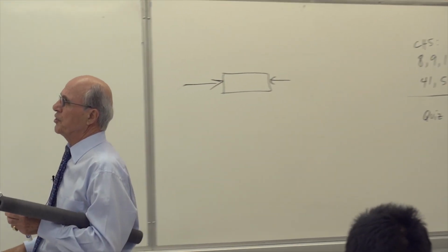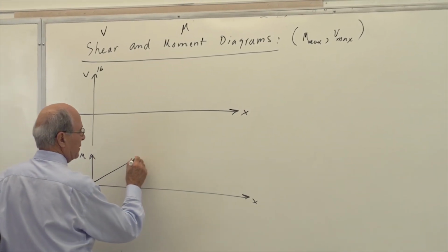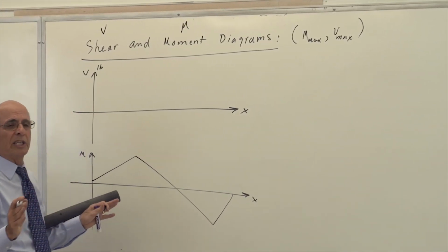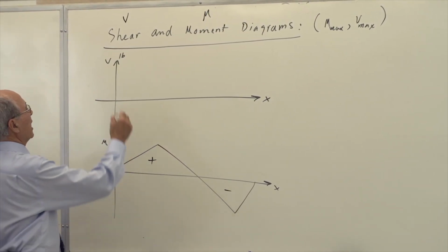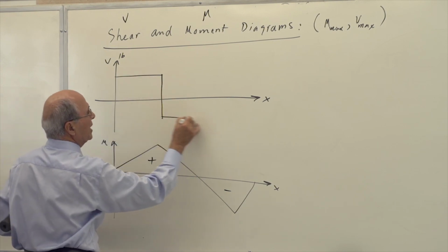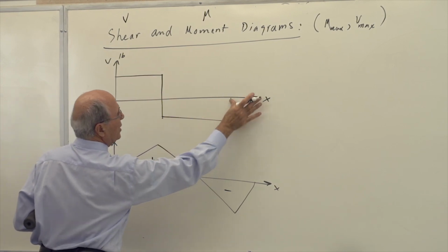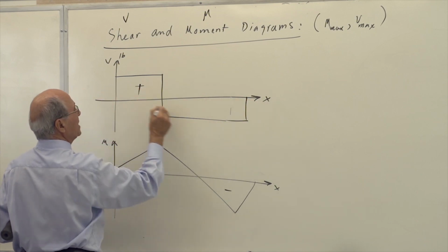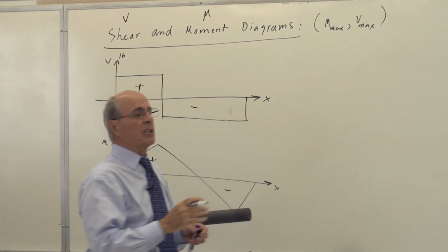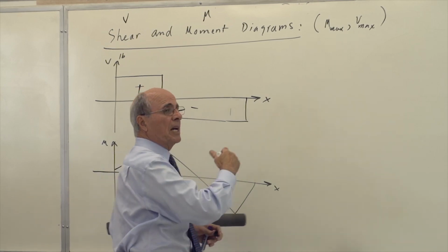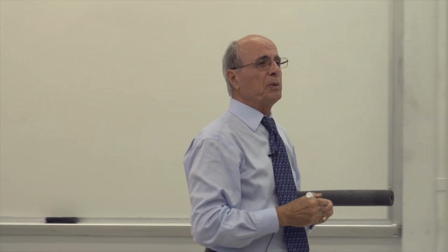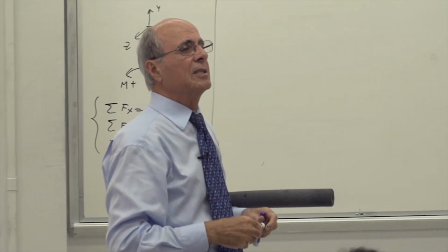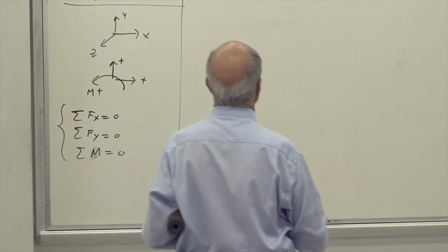Now about here is the same thing. If I want to draw, let's say my moment diagram becomes something like that, just for the sake of it. We don't know yet how it's going to happen. This part is plus, this part is minus. And let's say my shear diagram ends up like that. Later on we discuss how, but it has a plus side and a minus side. These are about stresses happening due to the shear and moment inside the body. Therefore, it should be either tension or compression, this and that. Is that understood? So therefore, we need a new sign convention.